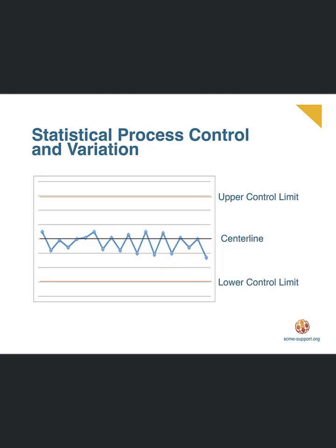Statistical process control assists in the proper management of variation. Special cause variation, or uncontrolled variation, is monitored and controlled with control charts. And, as technicians, it is important to understand the basic concepts behind these charts. Inline variation reduction is a major goal of statistical process control. Interestingly, the way in which products and process characteristics vary about some desired target value could actually provide valuable information that can be used to understand, control, and reduce the variation.